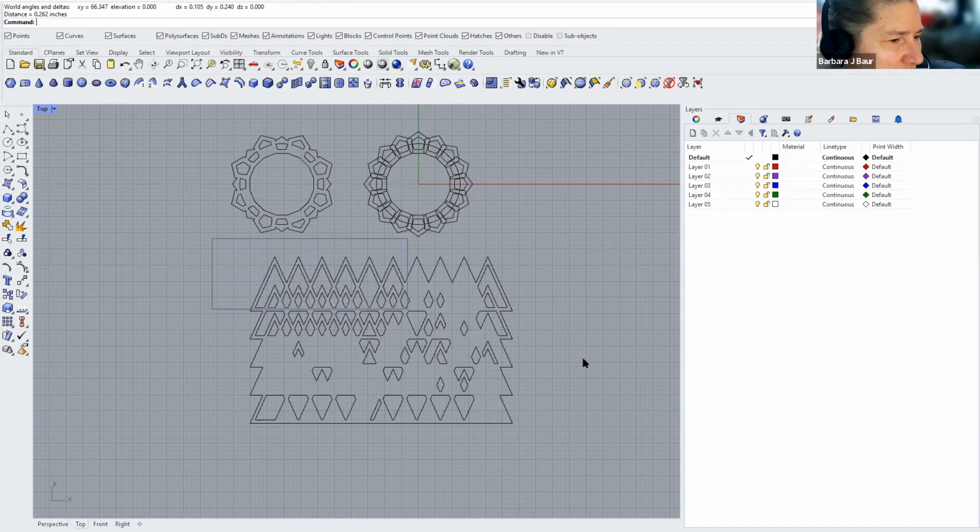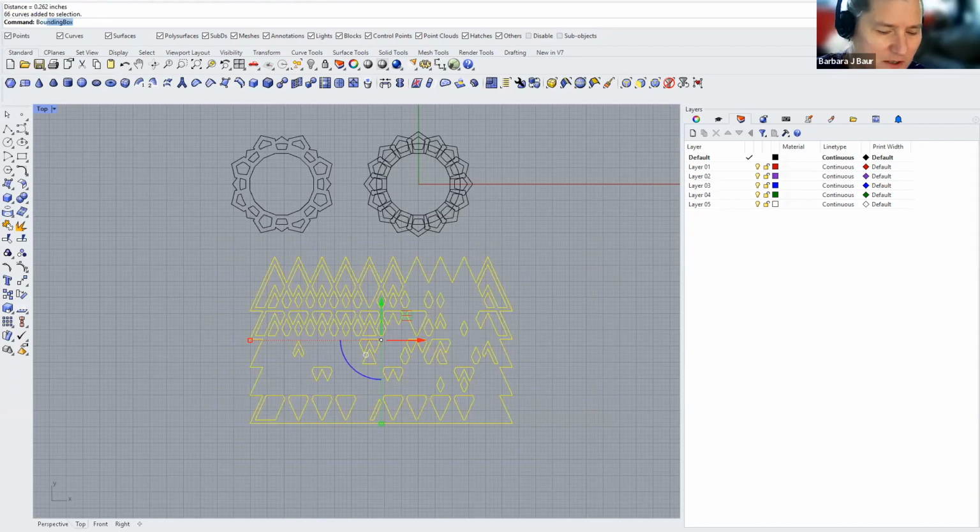So I could take this. Now let's do the bounding box again and see how big of a piece of acrylic I need for this. Output is curves, yes. And up here I need 15 across and 10 high. Our laser cutter bed is, I believe, 12 by 16. So this would fit, but I want to tell you, it'll fit just barely. I would probably scale that a little more in.